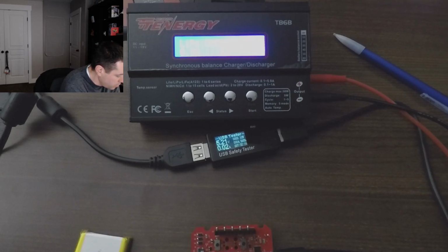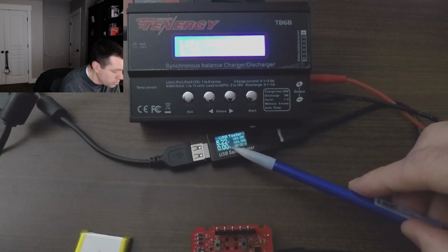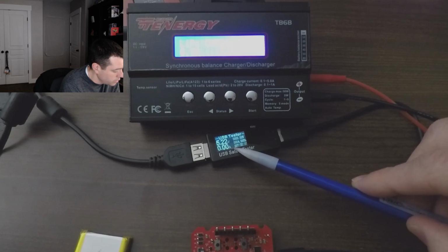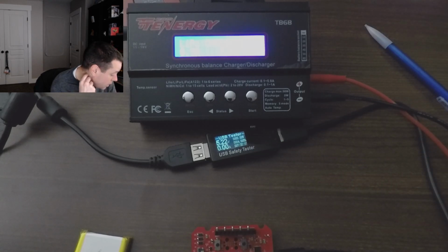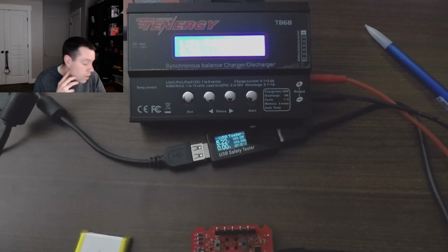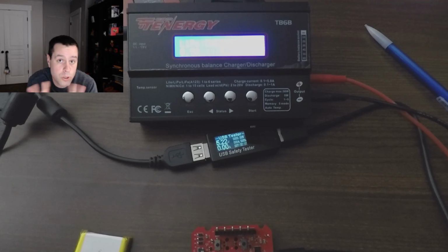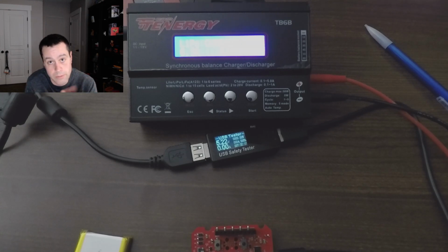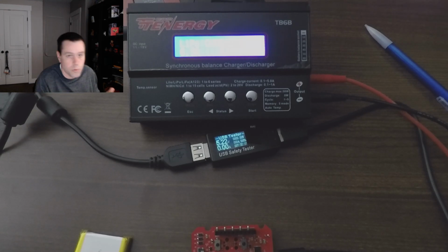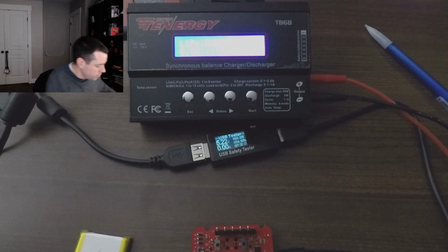So we're seeing 20 milliamps. 4, 5, 6, 7, 8, 9, 10. Look at that. It's so low that it's not even registering. Went to sleep. Okay. So it uses 20 milliamps, and in deep sleep, not even registering, as the other one wouldn't have either. So cool.